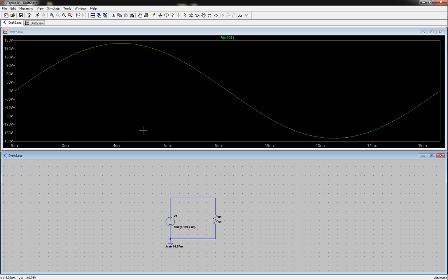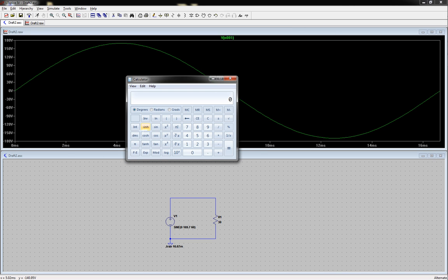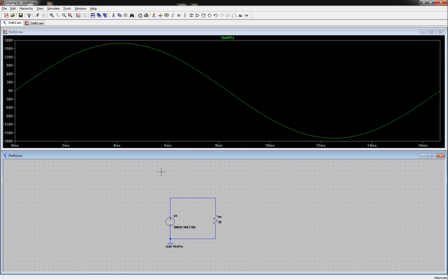So if you want to look at 2 times that, where you're looking at 120 hertz, so you've got 1 over 120, that should be 2 cycles worth. Actually, I messed that up. If you want twice it, so you can get 2 pieces of the waveform, it's going to be 2 times 1 over 60. Or you could just say it's 16 milliseconds times 2. But if you want to keep it in the frequency form, you'd have 2 over 60. And that's going to be 33.3 milliseconds.